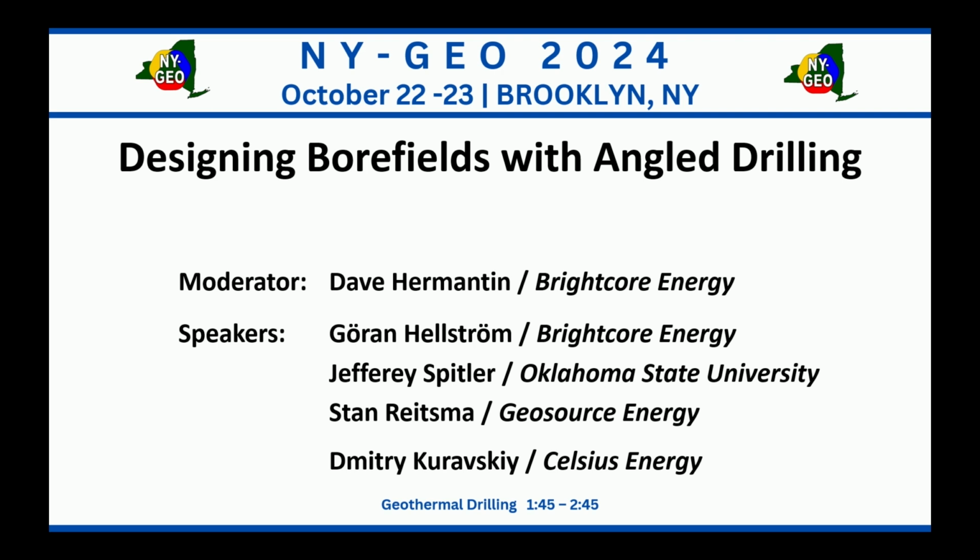Okay, I probably can start. Stan can add. There is definitely thermal interference, but it's taken into account at the design stage because the bores are closer at surface. We definitely lose a bit at the beginning, but because the bores at the bottom are spaced out, I don't know, 4 or 5 times more than traditional, you're gaining, and this is basically offset. As a result, this bore is more efficient.